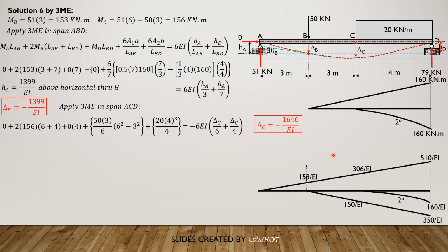So this is 3 theta B, because tangent of theta B equals opposite over 3, so the opposite is 3 theta B. And this very small distance here between A and the reference tangent at B is the deviation of A relative to B. So therefore, deviation of A relative to B plus 3 theta B, we just treat them as positive, equals HA supposedly. But we remember that theta B is negative, or HA, which is equal to delta B.